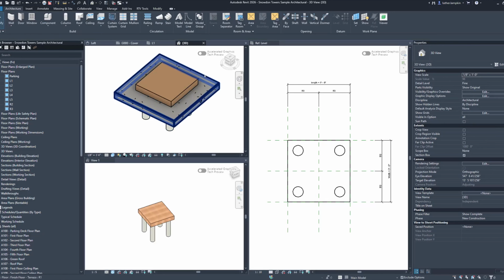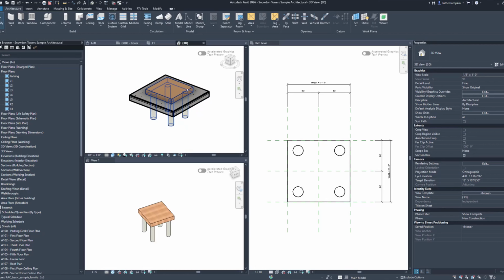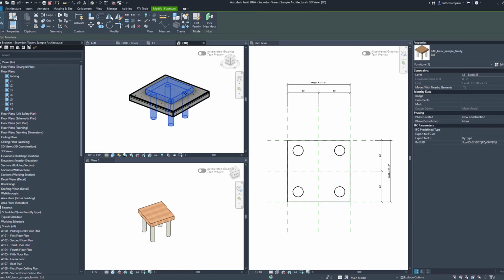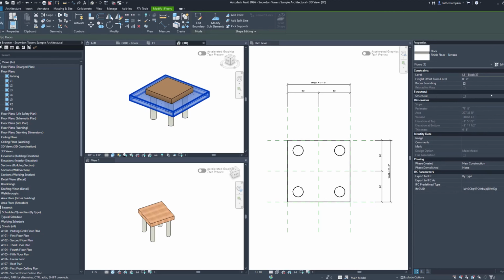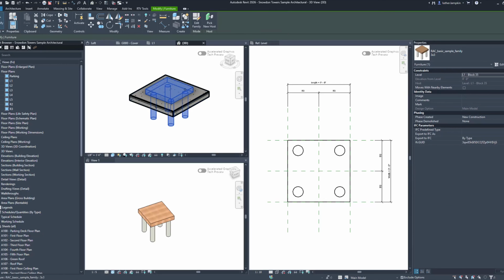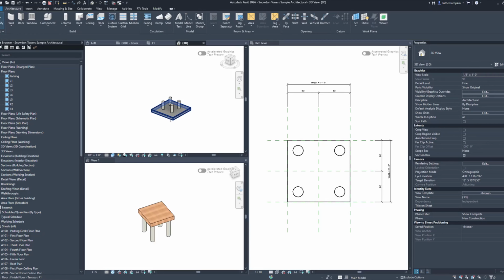Now, the only thing we didn't do is put it at the right height elevation. Right now it says this is at block 11-137. Click on the concrete. It says 37, and this one was 35. So we're going to change this elevation to 37. Now it's okay, it's still there. Just click on this box. It's a little visual section box, because it's cutting the section view based upon that.